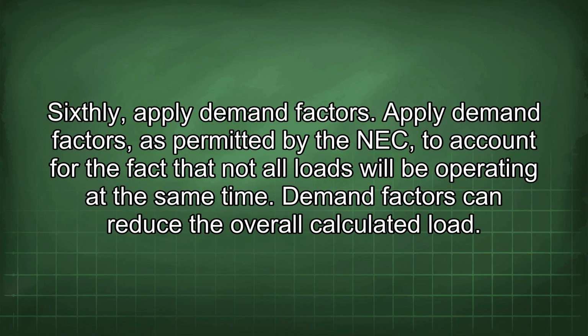Sixthly, apply demand factors. Apply demand factors, as permitted by the NEC, to account for the fact that not all loads will be operating at the same time. Demand factors can reduce the overall calculated load.